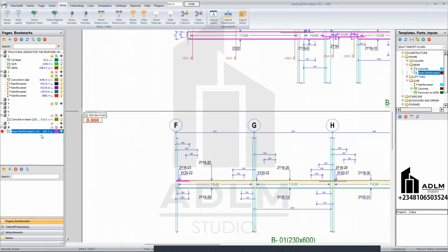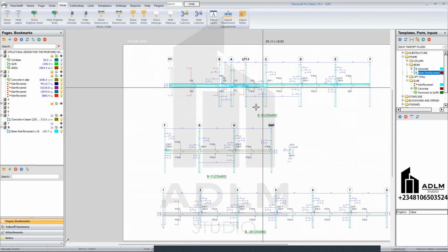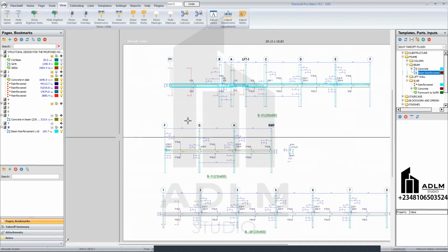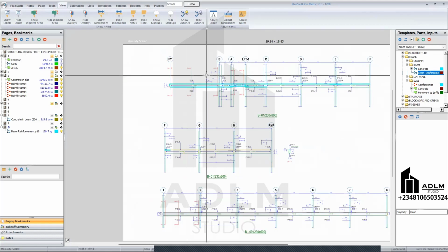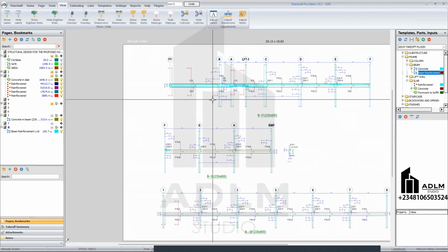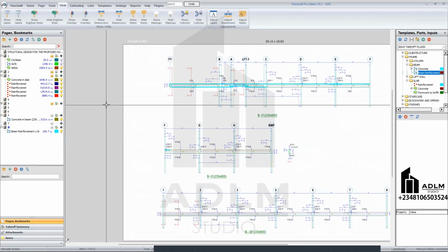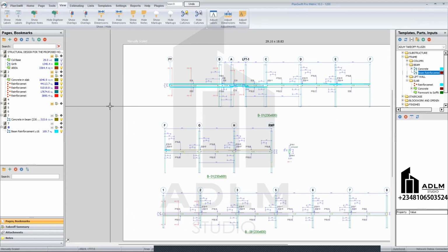So once you pick everything, you can just take the quantities directly to your view here. So that's how you want to pick the beams one by one from your structural drawing. That's how you go about it. Or if these details are the same as y20 or y16, just normal top and bottom dimension and all, you can use the one I explained initially. So that is how you go about your quantity takeoff for this.